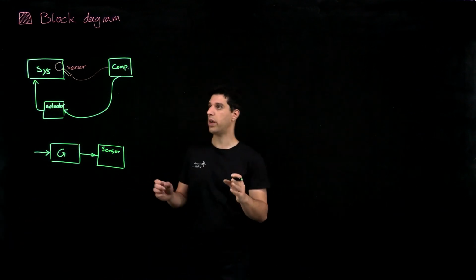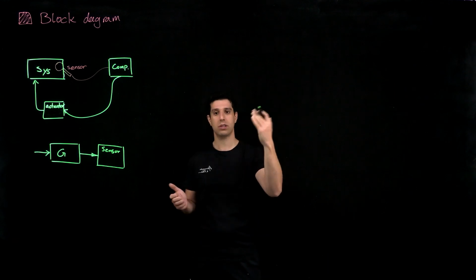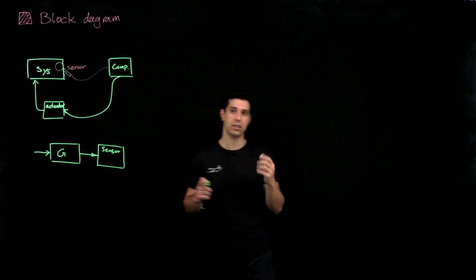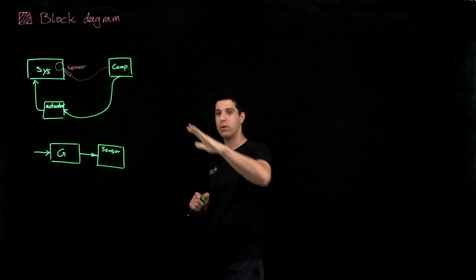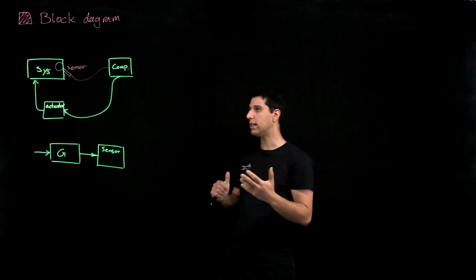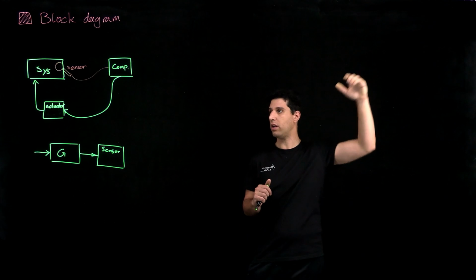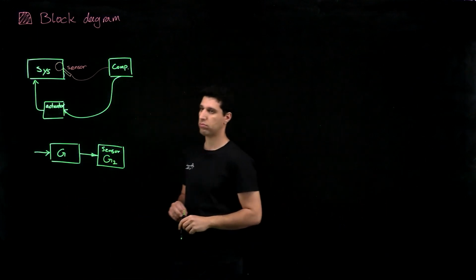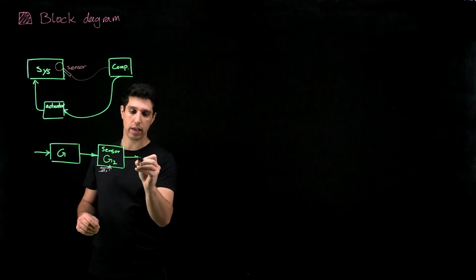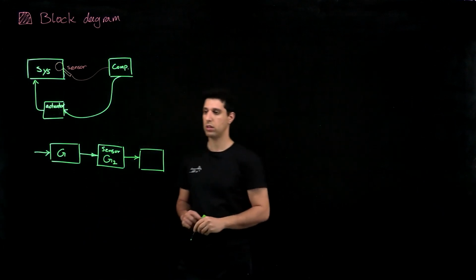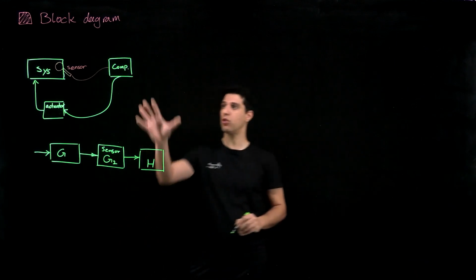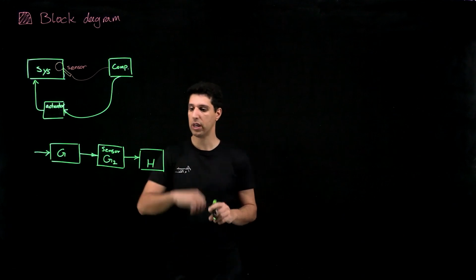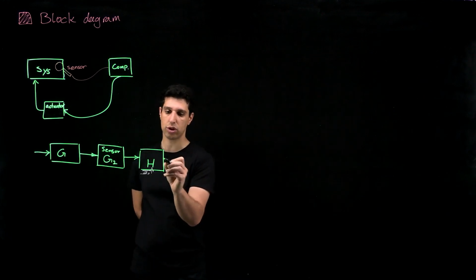So for instance, you can think of it this way: a physical thing happens, for instance the temperature or the position changes, but the sensor reads the output signal, for instance the voltage or some digital information sent to the computer, which might actually be a little delayed, or take some time to reach its final value. So it may have its own transfer function, G2. And this output is the information that is sent to the computer. The computer may have its own dynamics within its calculations. Depending on what the input is, it can do some calculations and produce some output. So this is the controller.